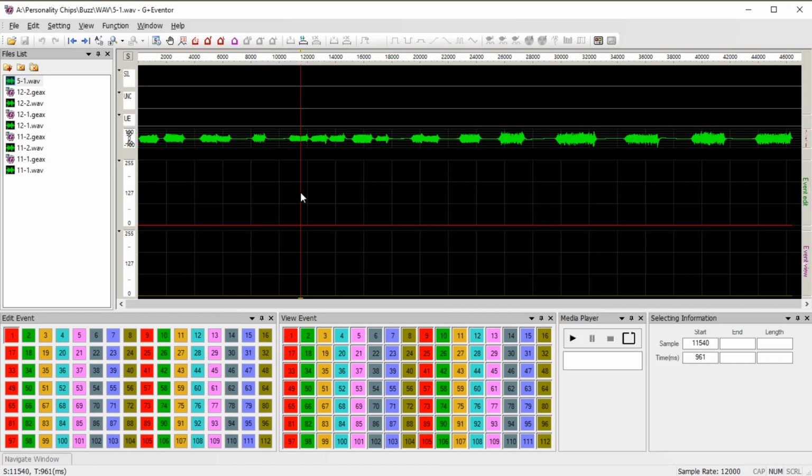For an R unit, one of the 3 LEDs that they have in the R unit heads will do that. The other 2 will do their own thing. So one of the 3 LEDs in the R unit head, if you pay attention, when an audio clip from Group 5 is playing, will start just blinking, whereas it normally doesn't blink. With the BB unit, when it plays an audio clip from Group 5, and there's only one, its LEDs will blink instead of fading in and out with the volume of the sound being played.